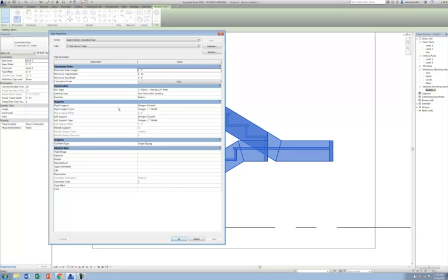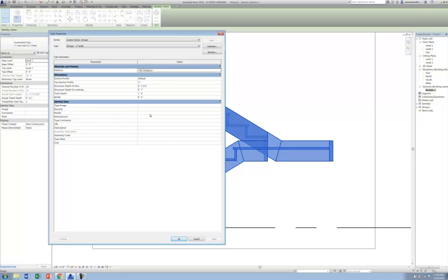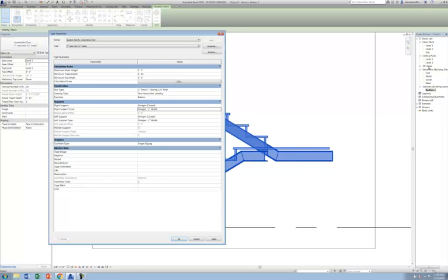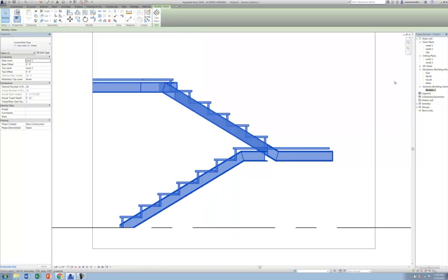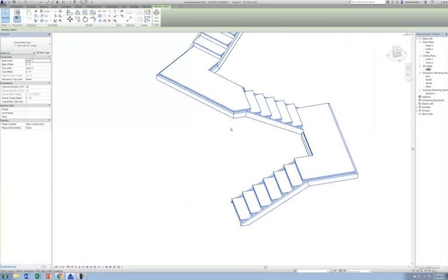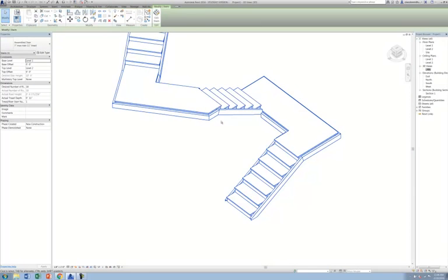And this time go to the right support type and hit the dot dot dot. And this opens up, again, another family, digging a little bit deeper down. This is the stringer type. And I can go to section profile, which you can see by default is set to default. And now that I've loaded in my C channel, it'll come in here. It is a little too small. And I'll hit OK just to see. You can also see we've got it facing the wrong way.